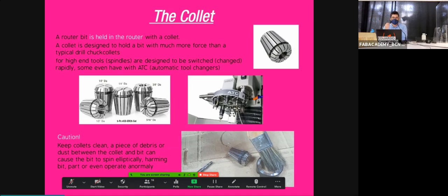So it's important, first, that the collet is clean. Second, that you use the appropriate collet. We have different sizes of tools: 1, 2, 3, 4, 6, 8, up to 20 millimeters thick. You need to take the collet that matches the size of your end mill. So if you use a 6 millimeter end mill, use a 6 millimeter collet. It's mandatory. And it's quite obvious, yes, but we have inch and millimeter collets. 1/8 inch is 6.1 millimeters, not 6 millimeters. You say it's only a 0.1 millimeter difference. Yes, but a 0.1 millimeter difference could make the end mill fly away or not. It's quite important.